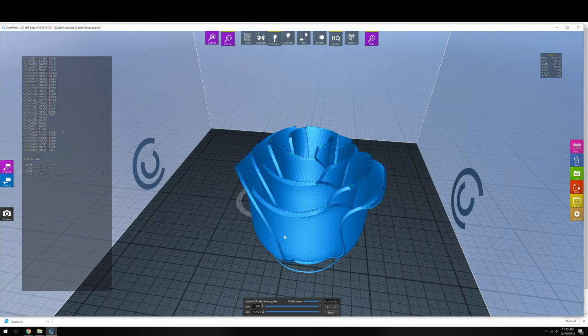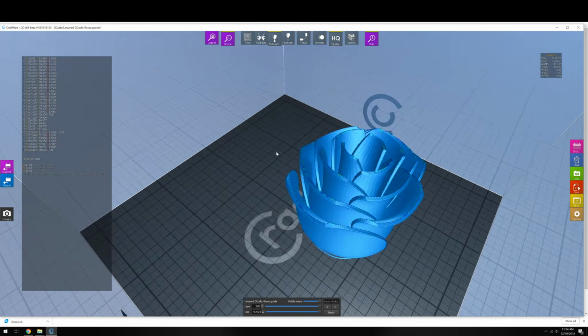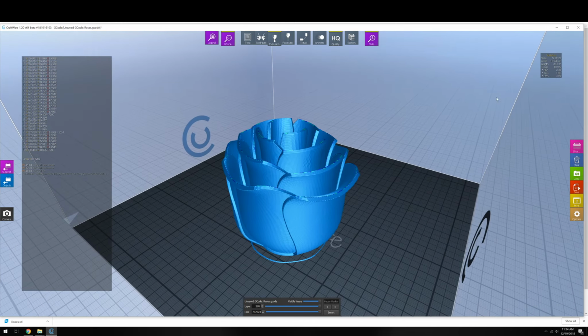On this screen, there's two things of note that you should pay attention to. Up here in the statistics box, it gives you an estimated time and then a length of material used. This time is typically wrong and is usually about 25% more. So for example, this one says it's going to take 5 hours, more than likely this print will take about 7 hours. As you have a 4-hour time limit, it is imperative that you make sure you're not excessively exceeding your time.